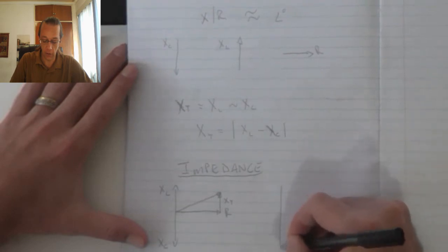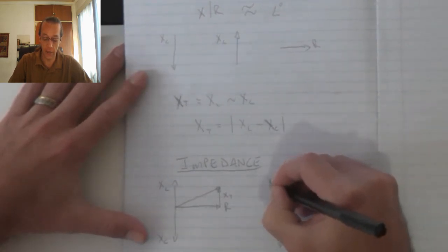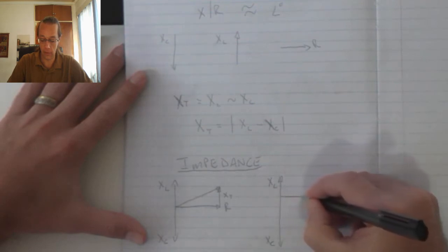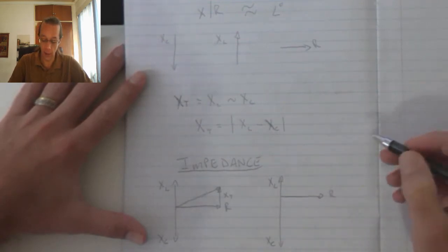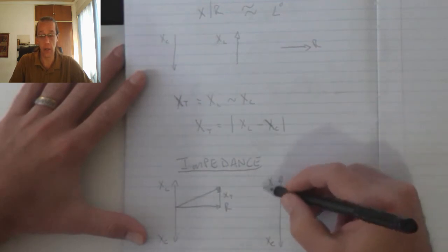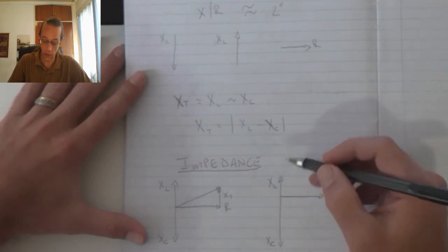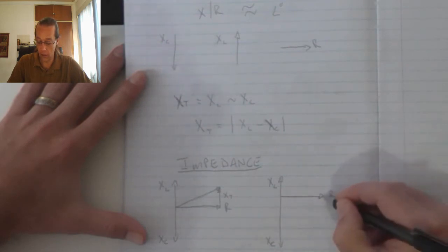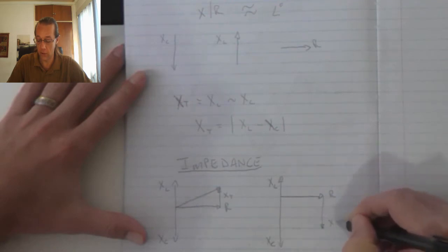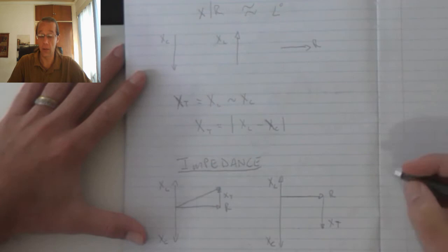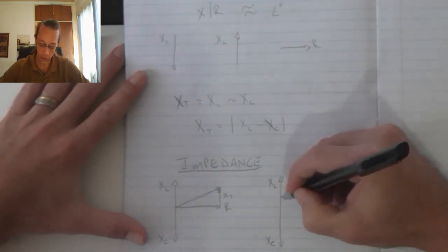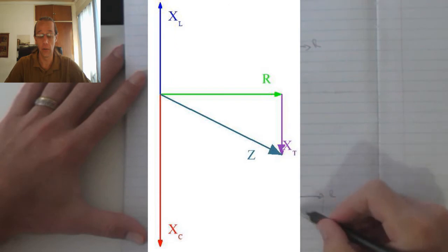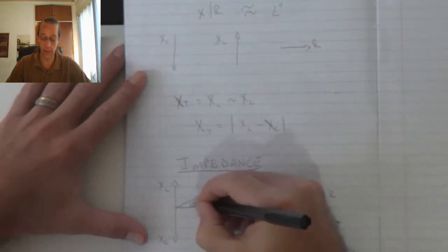Conversely, if we look at a scenario where XL is smaller than XC, that means R is going to be over there, capacitive reactance, and we're going to subtract the inductive reactance from it. That is going to cause that line to come out there, and my X total, or total reactance, is going to be indicated on the right over there, but below the resistor. Drawing this resultant in there will show the resultant angle. We will get to that at a later stage.